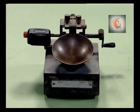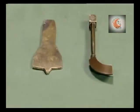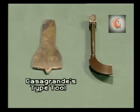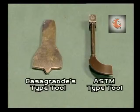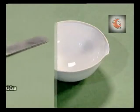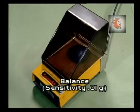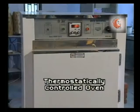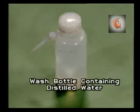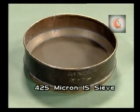The apparatus required for conducting this practical include a mechanical liquid limit device, grooving tools like Casagrande type and ASTM type tool, porcelain evaporating dish, spatula, balance with sensitivity to decimal 0.1 gram, thermostatically controlled oven, wash bottle containing distilled water, sample containers and 425 micron IS sieve.